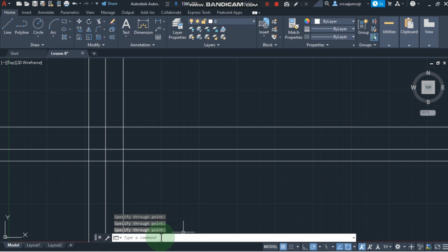So we will specify a distance, the X line is offset from the selected object, or we can create an X line offset through a line passing through a specified point. So let us try it again. XL, offset, what distance, for example, we want a distance of 5. So from that 5, let us make an offset.